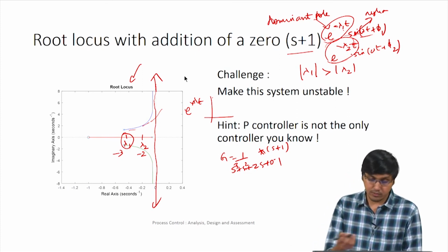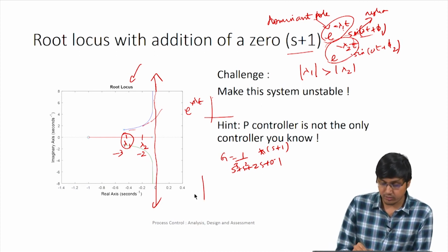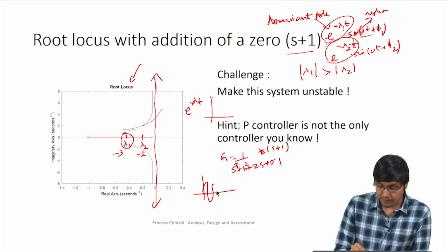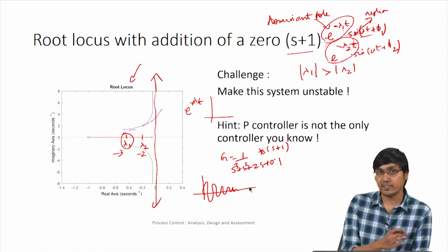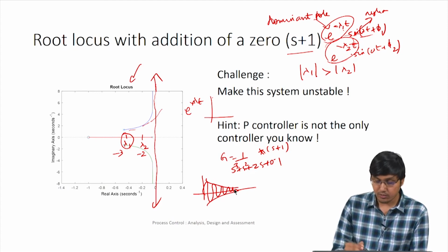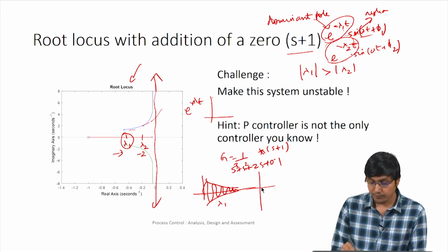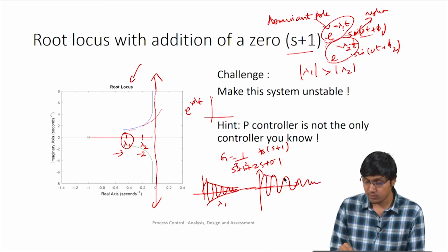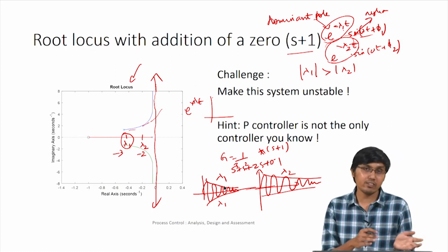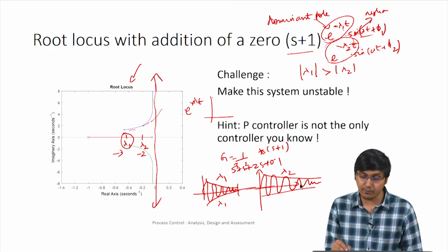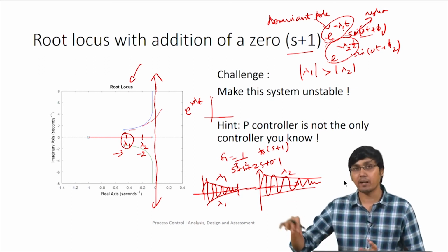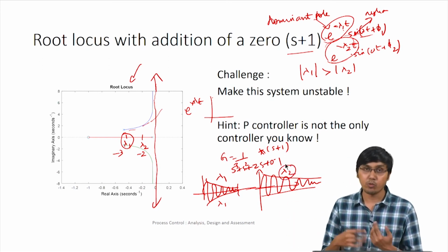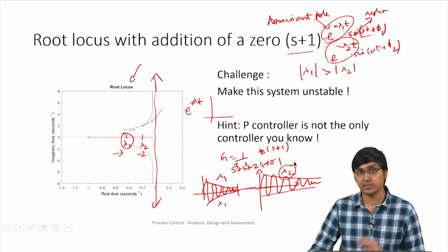To summarize, both lambda 1 and lambda 2 are stable, on the left hand side of the S-plane, so both are going to fall down. But lambda 2 is going to take a much longer time to fall down. Lambda 1 is falling faster, getting to 0 faster, but lambda 2 takes some time to go to 0. So basically lambda 2 is more significant than lambda 1. So lambda 2 is the dominant pole. That is what we want to say.